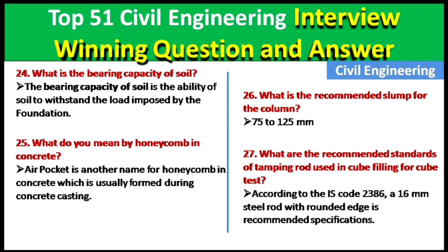Okay, now point number 26 is what is the recommended slump for the column. Okay, guys, this is very important and the slump value for the column will be how much? 75 to 125. Okay, it should not be less than 75, it should not be greater than 125 mm.